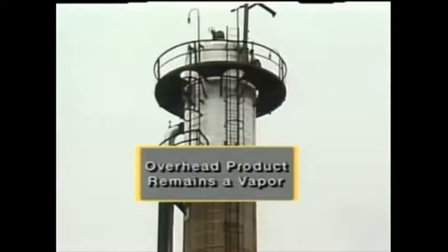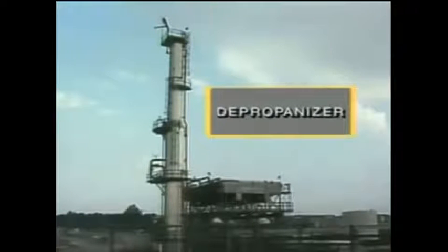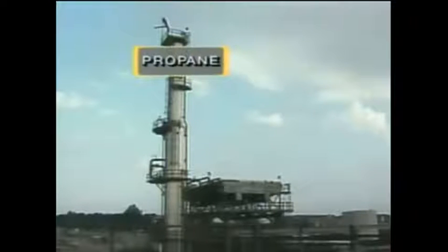Many distillation towers operate at or near atmospheric pressure. There are some distillation towers, however, that are designed to operate at pressures lower than atmospheric. These types of towers are called vacuum towers. Vacuum tower operation is based on the fact that pressure affects the boiling temperature of a liquid.